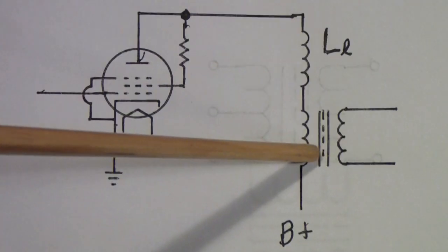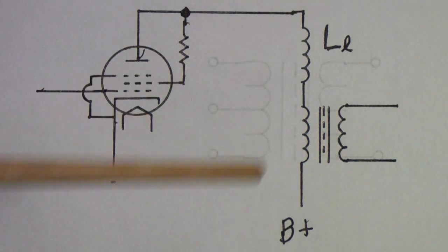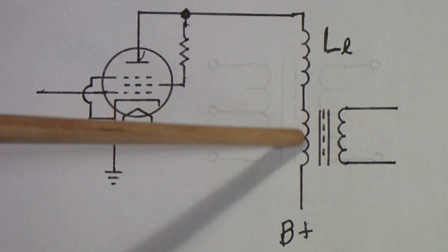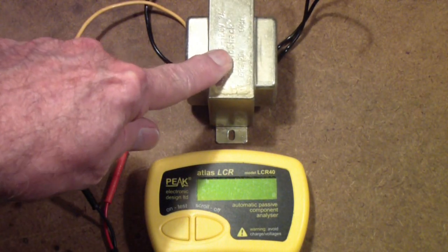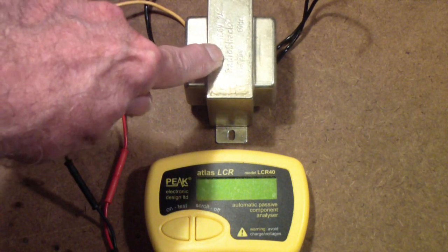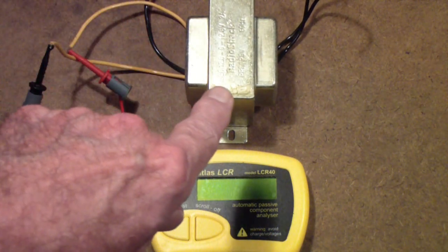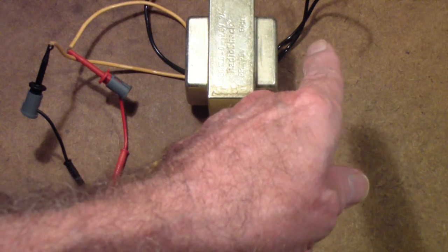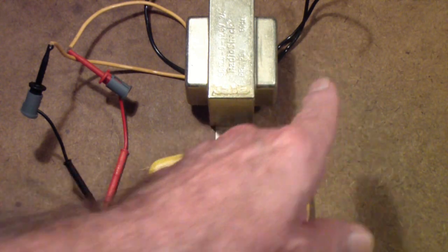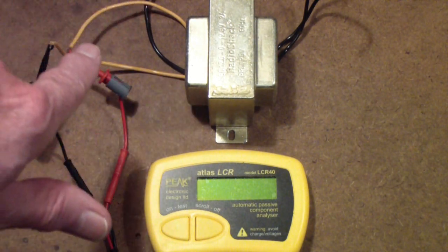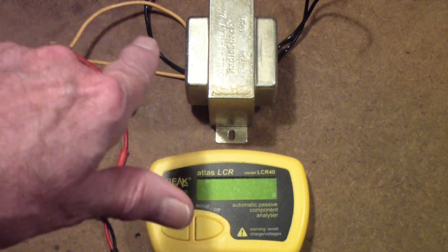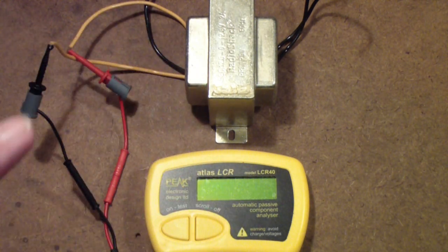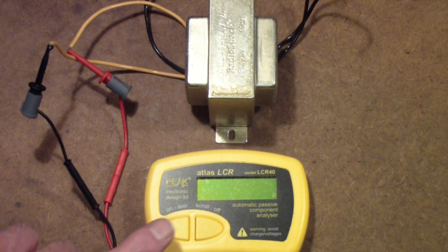So suppose we have some transformers and we want to know which ones have the most leakage inductance. So on the bench I have a transformer. In this particular case it's a power transformer, and normally it's connected by hooking the 110 volts to the primary over here, and you get 25 volts between the two yellow wires, it's center tapped. So basically it's a 12 volt center tapped output. But I'm going to use it to demonstrate how you measure leakage inductance, also how you measure inductance in general.